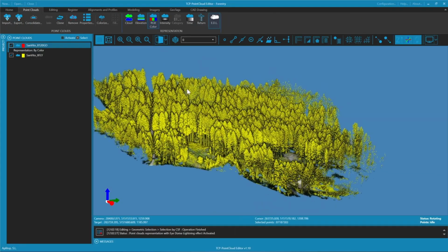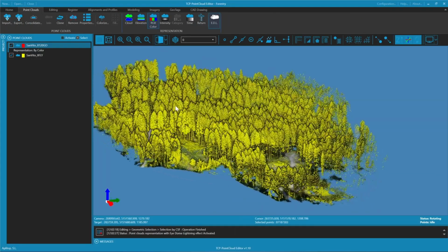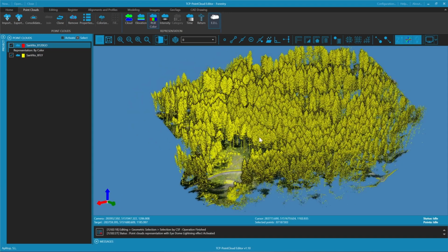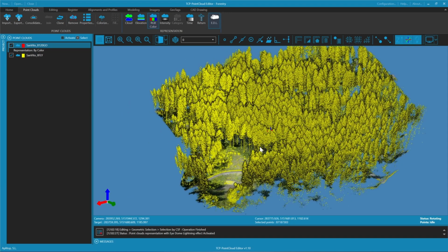So it's very weak against low noise points, and also at the borders you're going to see, because we don't have so much density and we miss the ground points, there is where we can have more issues, but we'll fix it later. So we run the filter at a resolution of 0.2 meters and let it work to find the ground.